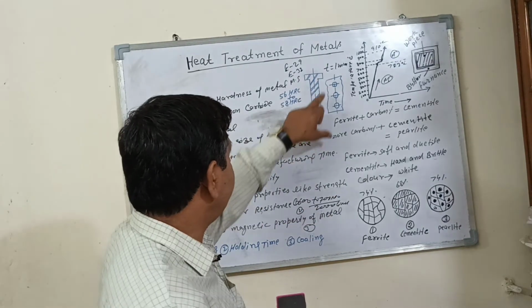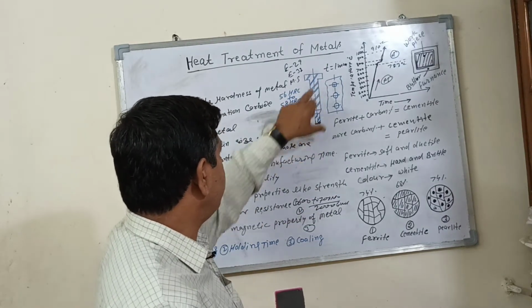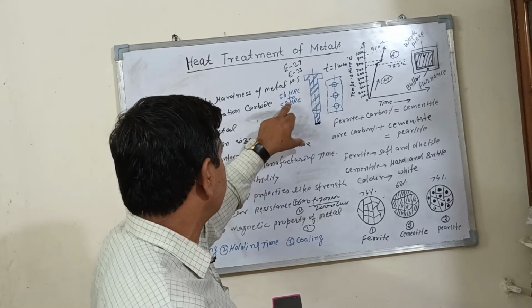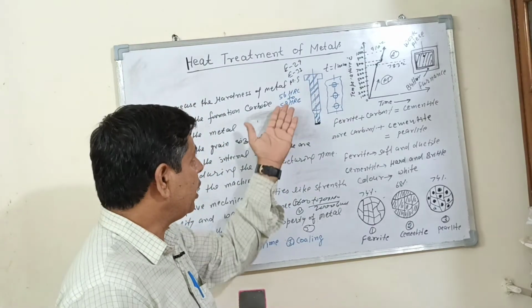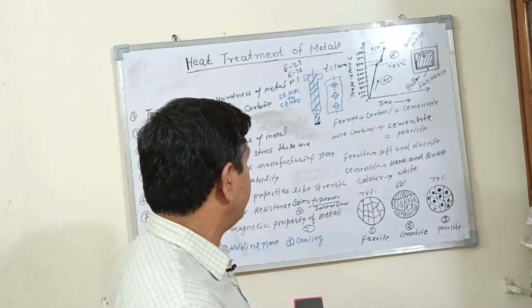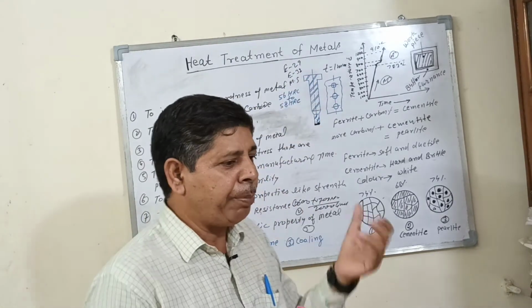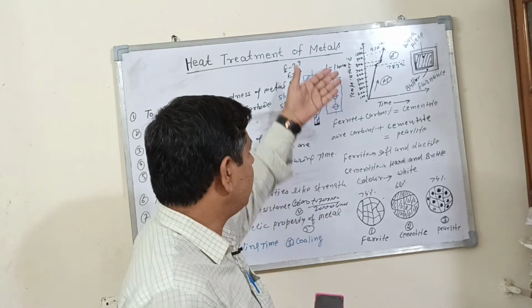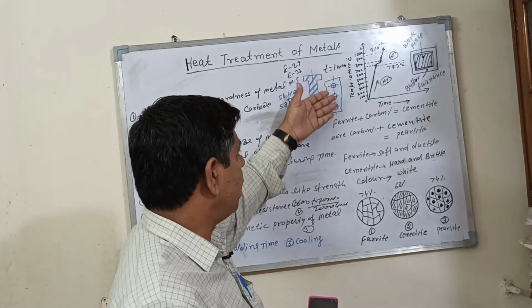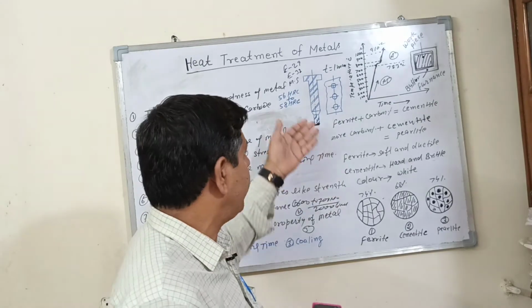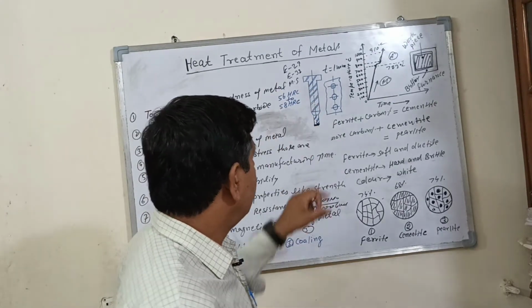The hardness of the metal should be taken as 56 to 58 HRC. HRC means Rockwell hardness number. This type of punch is mounted on a hand press or power press. You get mass production and high grade accuracy without any breaking of the punch.